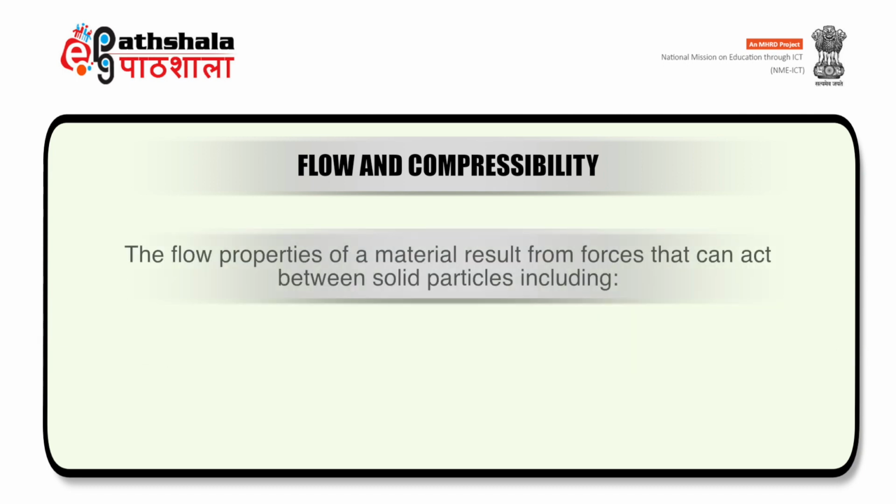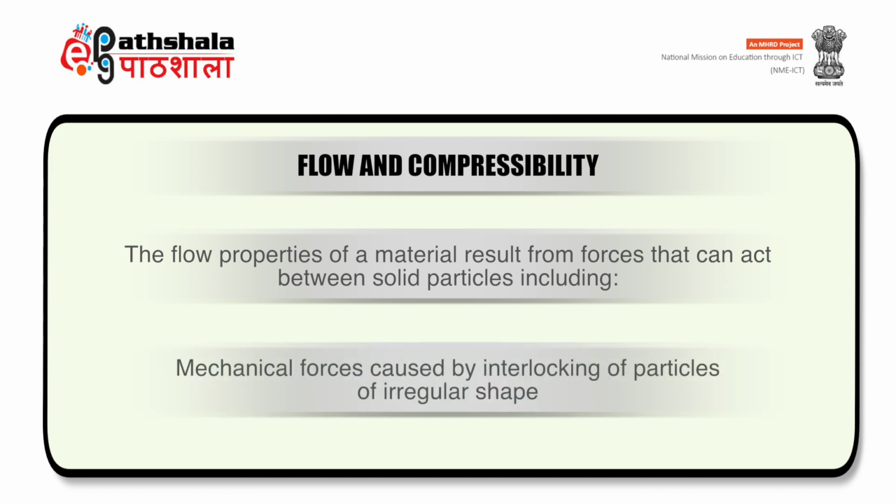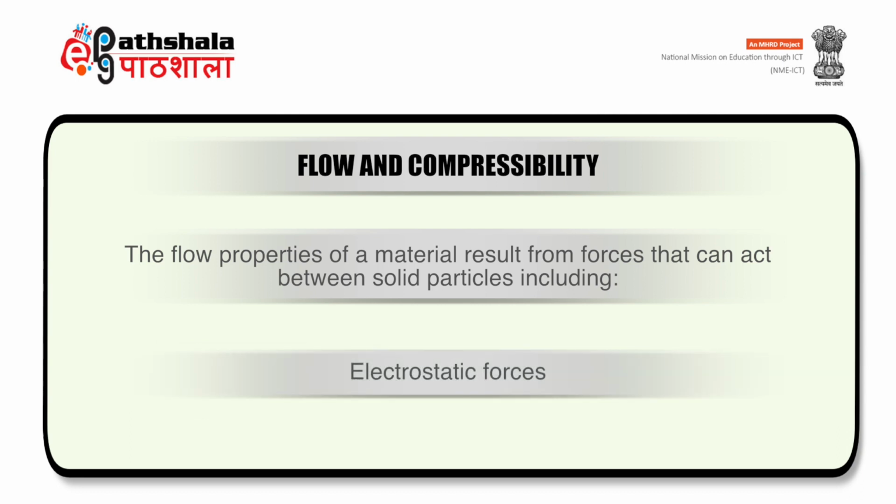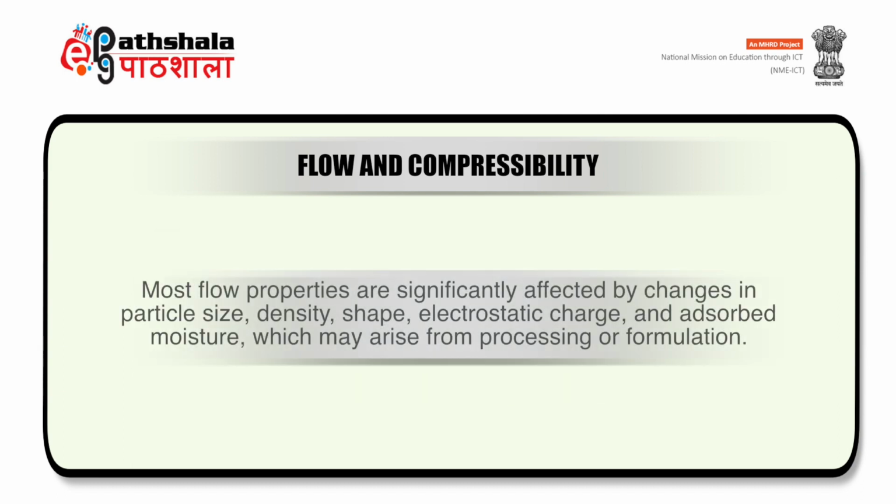The flow properties of a material result from forces that can act between solid particles including frictional forces, surface tension forces, mechanical forces caused by interlocking of particles of irregular shape, electrostatic forces and cohesive van der Waals forces. All of these forces can affect flow properties of a solid. Most flow properties are significantly affected by changes in particle size, density, shape, electrostatic charge and absorbed moisture, which may arise from processing or formulation.